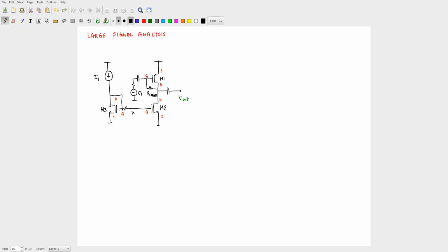Because of that, it sets up a VGS voltage here, that VGS biases M2, correct. That current is flowing in here, and then you have a drain feedback, and that sets up what the gate voltage should be, and then this M1 gets biased. Okay. So, in this way, the range about which VG can move is actually very small, right, because of the fact that there is this feedback loop working and all of that.